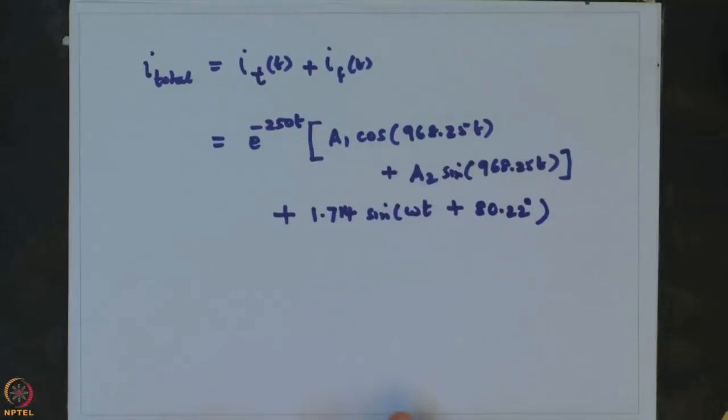One important thing you might have noted is that because we are considering linear networks, which are the networks that power electronic circuits have to deal with between two switchings, when we apply a sinusoidal forcing function, our response is also sinusoidal, and its frequency is the same as the applied forcing function's frequency. Only its magnitude and phase will be different. I would advise that you verify this and be confident about this point.